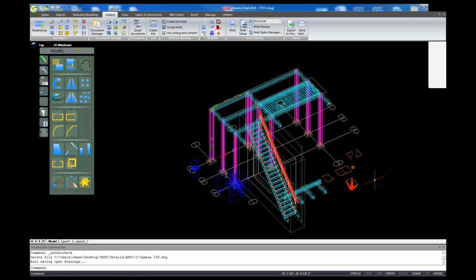If the token is there on the list, that means that it will work. But which file are they talking about? Maybe, in theory, it has to be the 2D DWG name. You can do the test with this token. The token is the last from the bottom, named file name. So just follow the steps as we did last time, where I showed you how to create your own attribute. That will do the job.